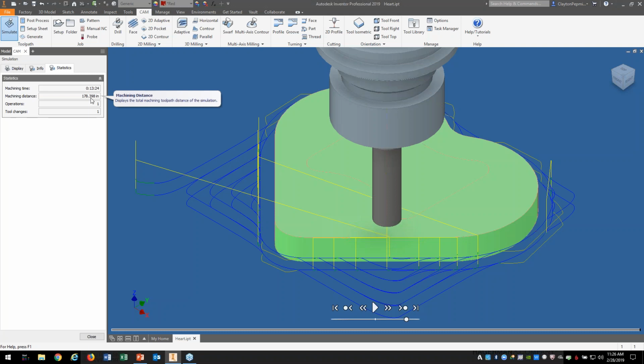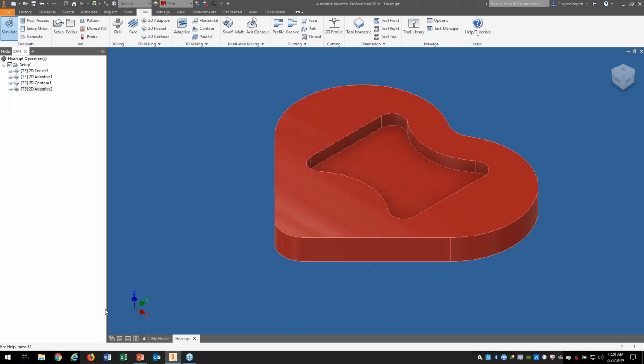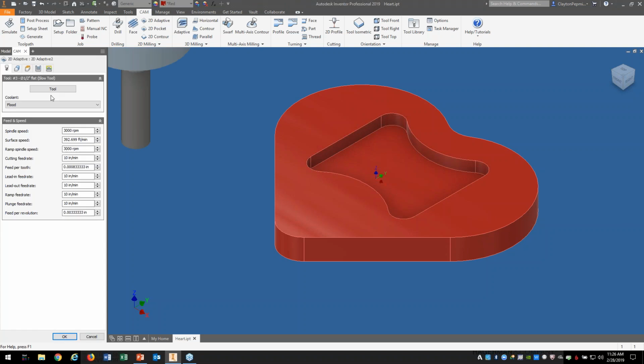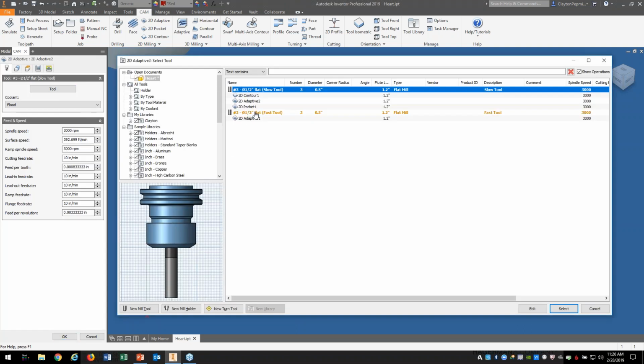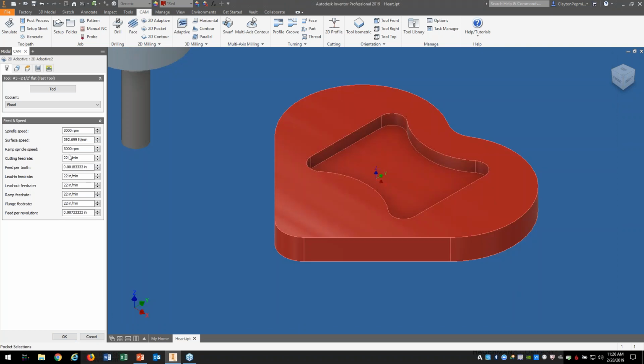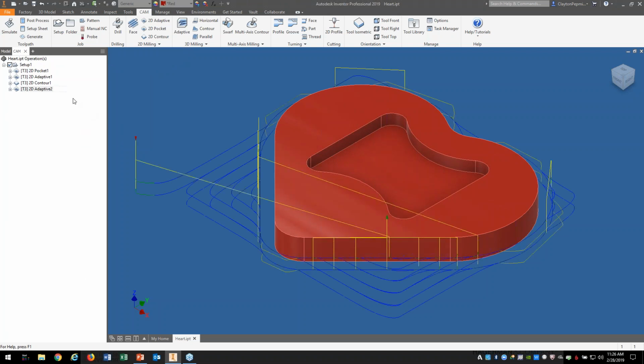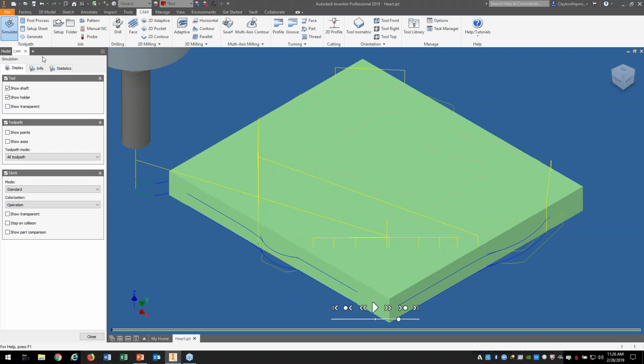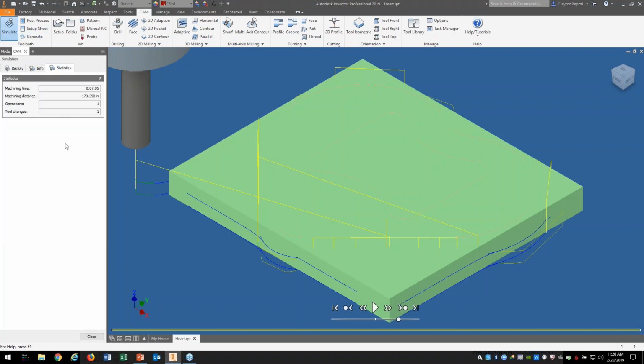Now, that's just everything identical. Same feed rates, same everything. Now, because I'm guaranteed that my stock removal is never going to take more than 1/2 of my tool, what happens if I edit that and switch this over to the faster tool? Maybe I run it 22 inches a minute instead of the traditional 10. If I do that, take a quick look at the simulation. I don't need to run, I'll just look at the statistics. I can actually machine the outside of that part in 7 minutes. 7 minutes and 6 seconds.